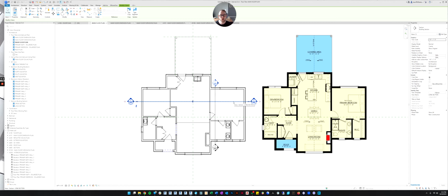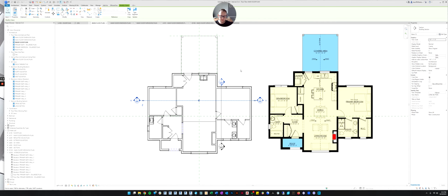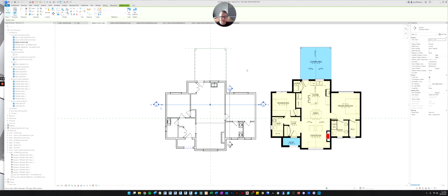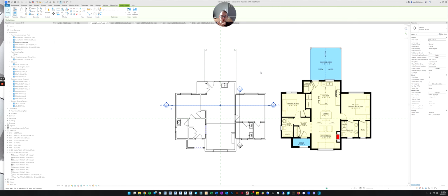Sections we usually do show in the floor plan. Those are important so that the person who's looking at the drawing knows where a section is being cut. So let's do our first annotation then. One of the most important annotations in a floor plan is to label the rooms. But before we can annotate the rooms, we have to create rooms. And Revit will help us do that.